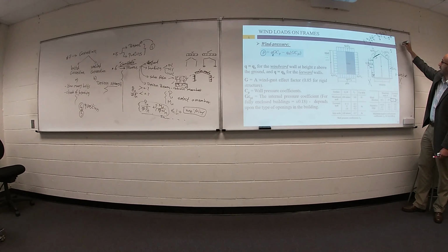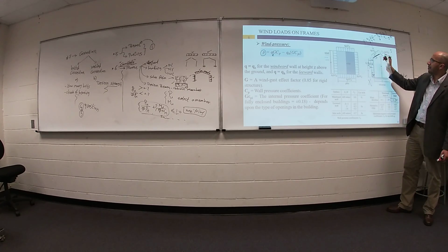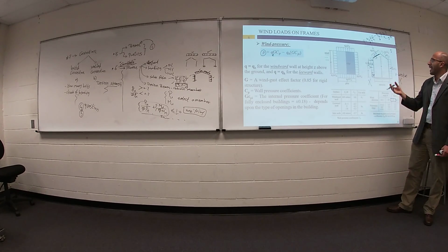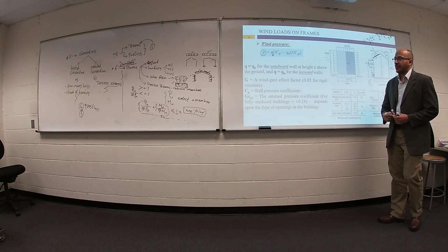I use local axis most of the time for any inclined member, because with an inclined member and this force, I cannot figure out if this value is a horizontal value or vertical value. So I will use the local axis for these members only.